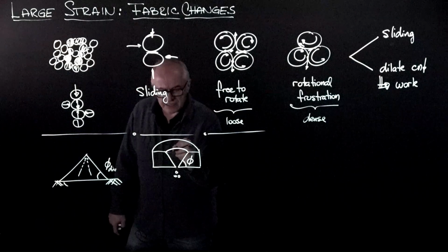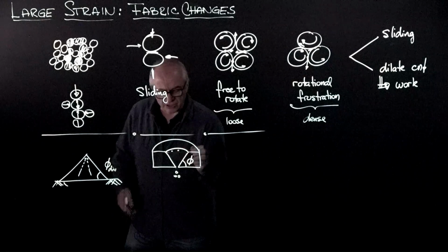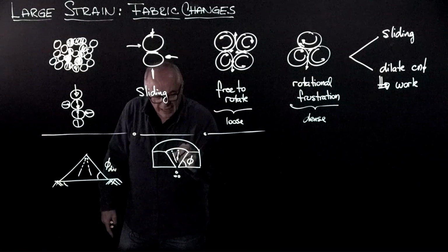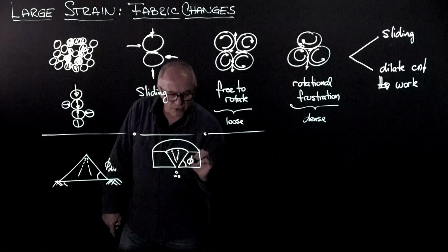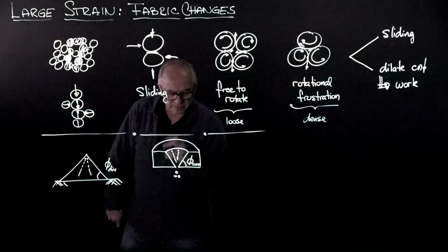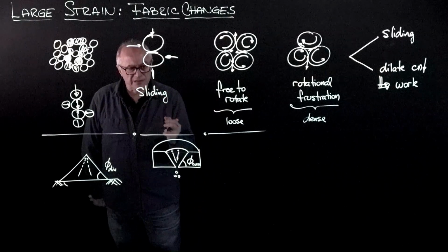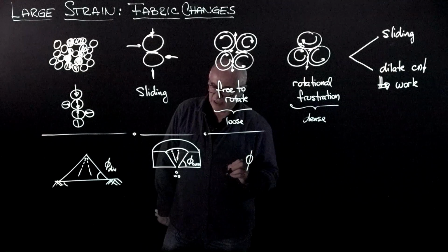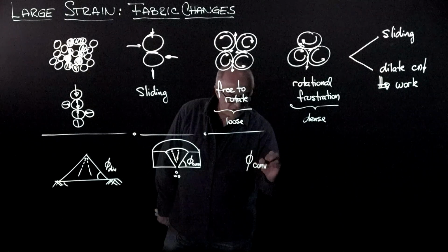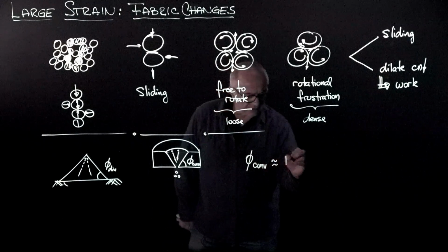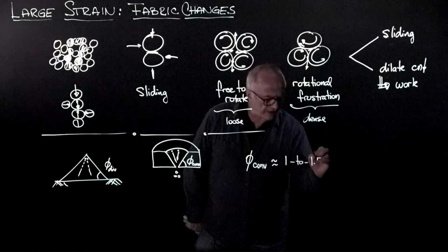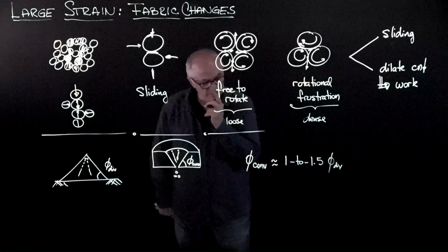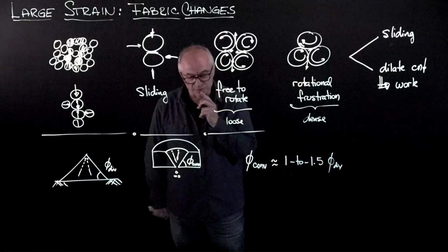However, two grains here that are coming from the top, as they migrate, they converge towards the orifice, and this will be an angle of repose for convergent flow. And when you do these experiments, you will see that the angle of repose in convergent flow is somewhere between 1 to 1.5 the angle of repose in divergent flow, or the friction angle in divergent flow.